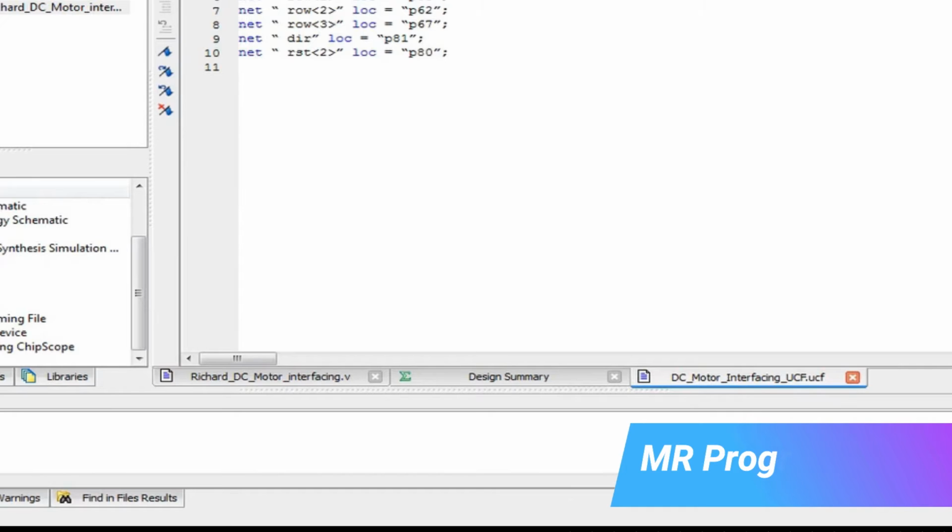If not, say for example, instead of pin 55, I use some other pin, then there is no information getting passed, which means there is loss of information. And these are all standard, company specific. You get this information from the company and we follow the specific pins accordingly, just like how your normal ICs will have ground at one particular pin number, then your VDD at one particular pin number.